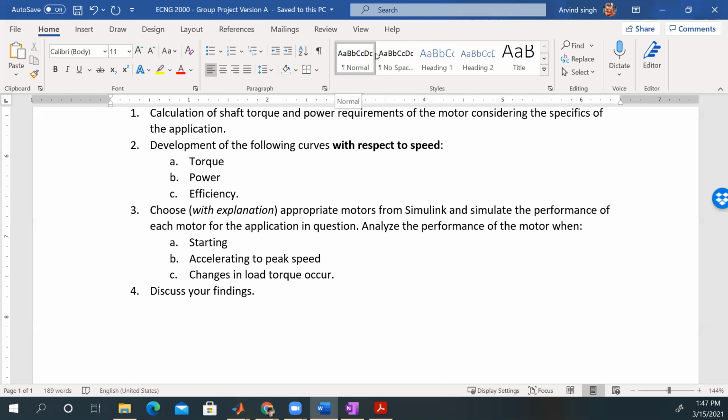So if you have an application and the only way the torque is being met is with a very high power motor that might be too big, you could use gears to increase the torque and reduce the speed of a smaller motor that might have the power requirements. These are things you could look at in your motor selection in the project. You could say, okay, this motor does not meet the spec, but we're going to gear it down using a particular gear ratio, right? And all these are things you can pick up pretty quickly with some independent study,